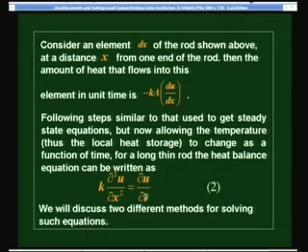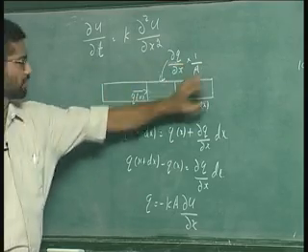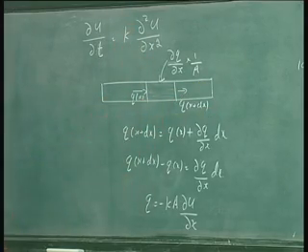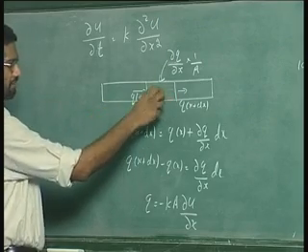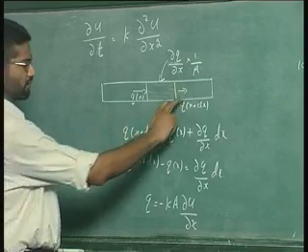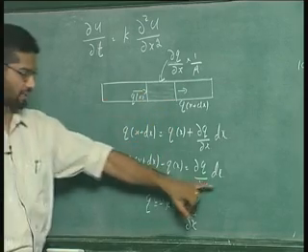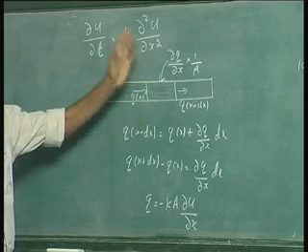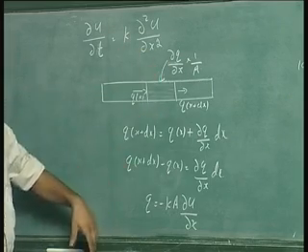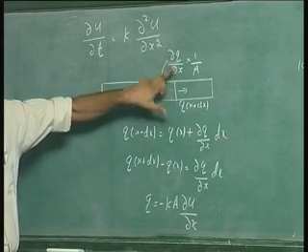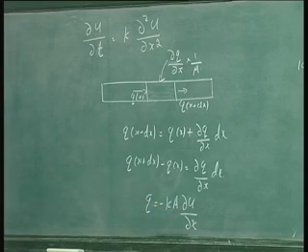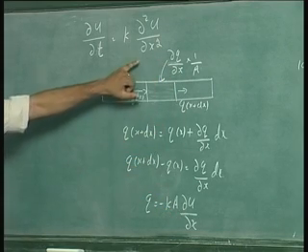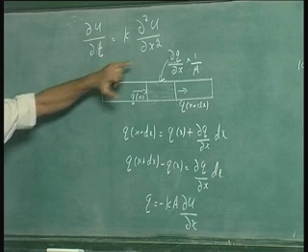So that is one case where you get this equation: take a long thin rod, insulated on the sides, so heat comes in here and goes out there, and across the cross section we assume the temperature to be uniform. If we take an element of length dx, what comes in here is qx, what goes out is qx plus delta x, so retained is del q by del x into dx. So the heat retained per unit cross section per unit length would again be 1 over A del q by del x, but we know q is kA into del u by del x, so we get the heat retained is actually del square u by del x square, and that retained heat is actually used for increasing the temperature there.